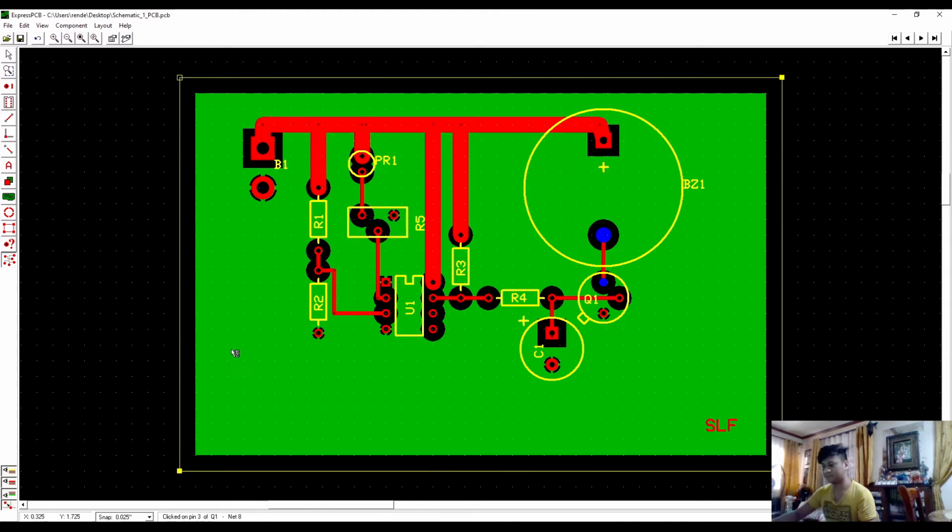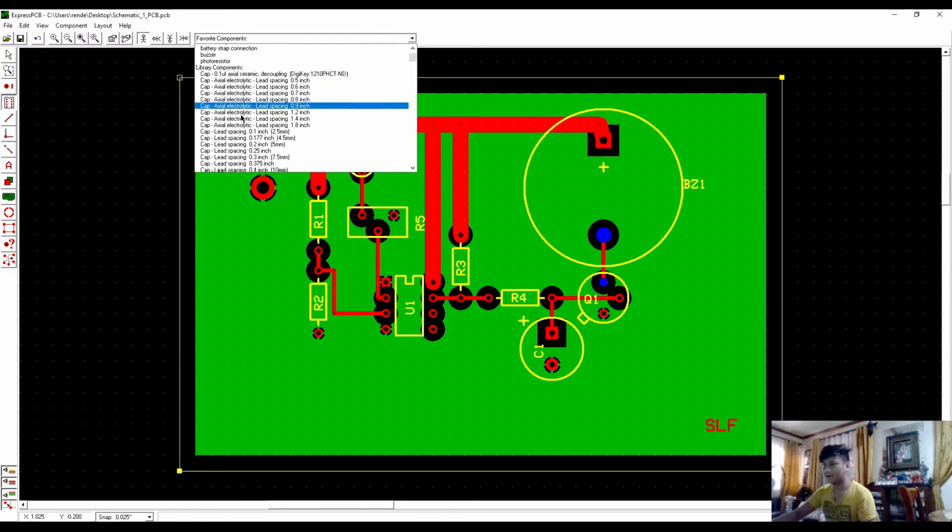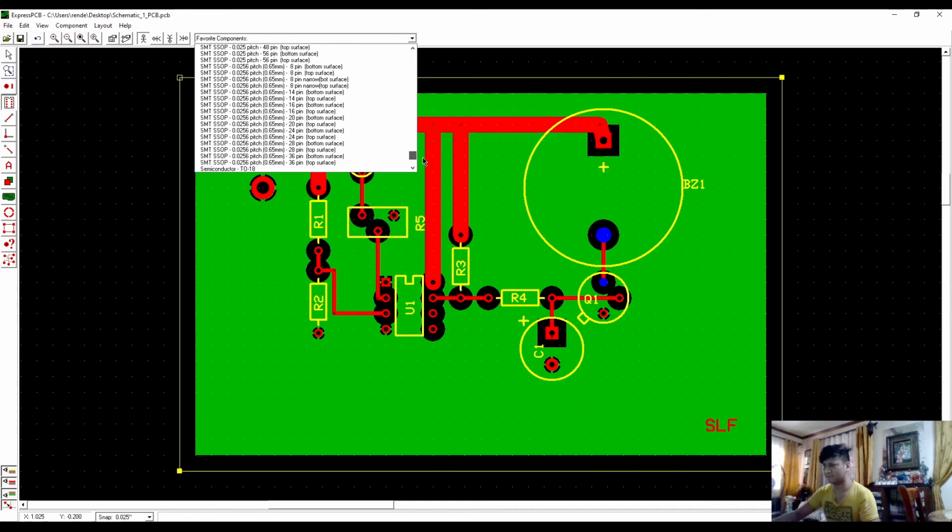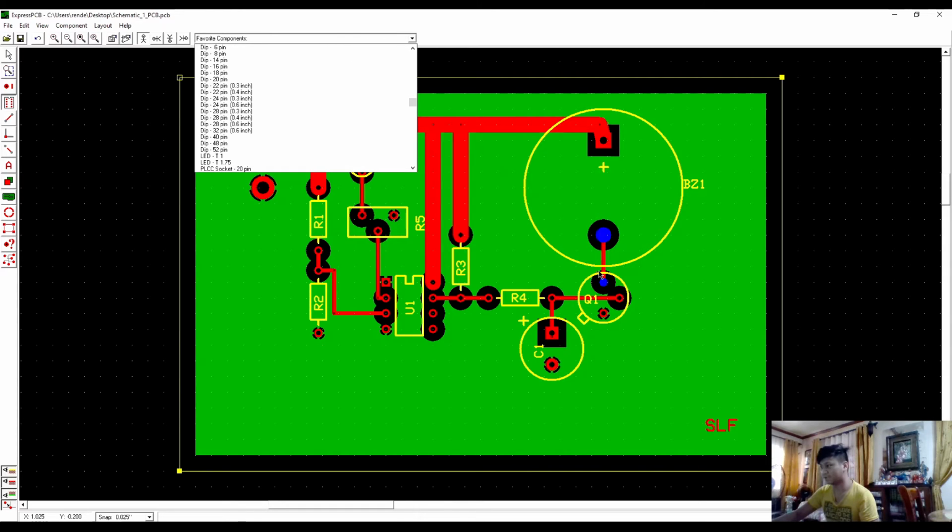By the way, I will explain how to put some of these. Let's try one. As you can see, we can put the components in a PCB. If you need something like a semiconductor, which is this one, we have different models depending on your liking. So here is the dip switch. We use a dip switch because in the schematic, it is a comparator 8 dip switch, so that's the keyword. So we put this and click and place it.